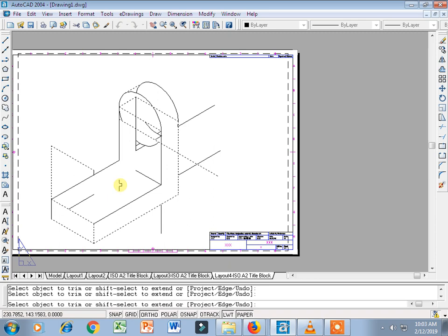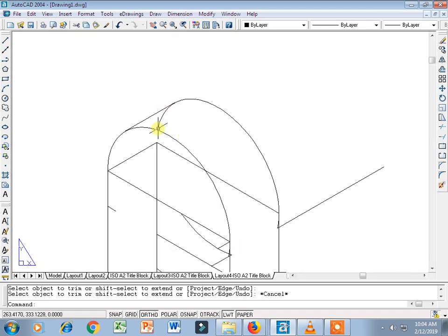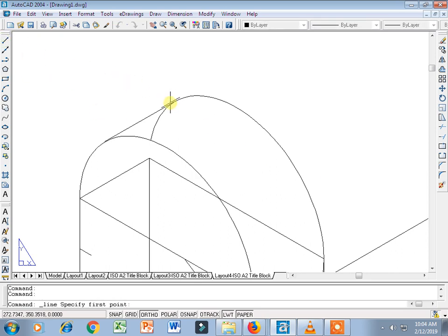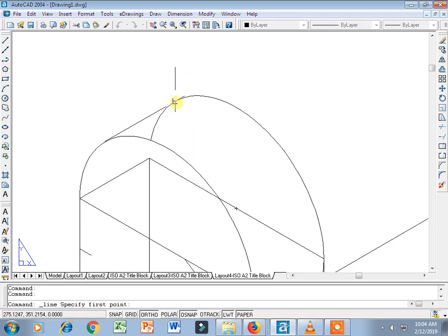Once the intersection is over, we cannot delete that part, so preferably you first select the part which is in intersection, so the rest of the thing you can select and delete directly. Okay, so we'll escape and we'll come out of it. Now here I don't want this portion, but if I cut it, the entire thing is cutting, so we'll make one more line here, make O snap on, we'll make one more line here which can create an intersection.